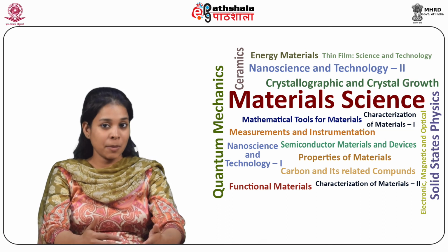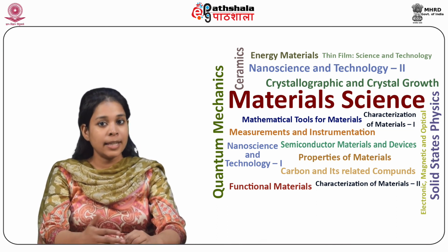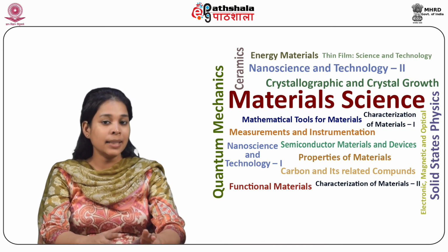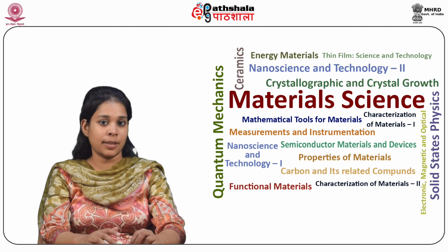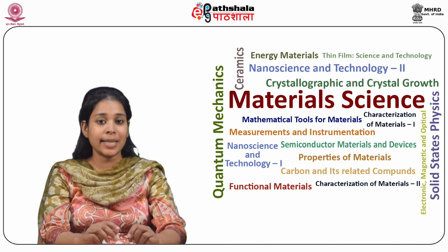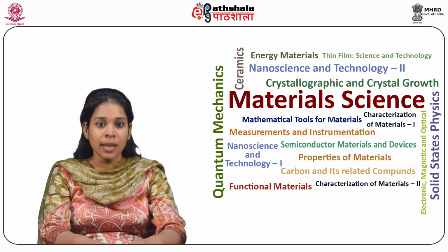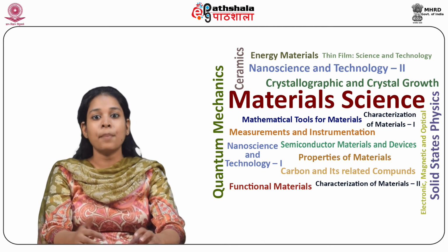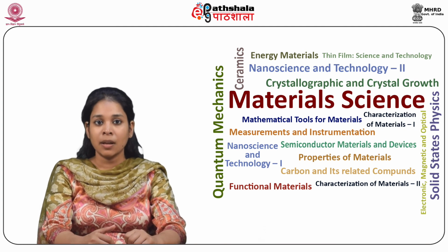So the pressure may be uniaxial or isostatic, and for these cases we have read that it is hot pressing or hot isostatic pressing. These pressing techniques are quite expensive and are used to sinter difficult ceramic products. They can produce some parts with nearly 100% density.